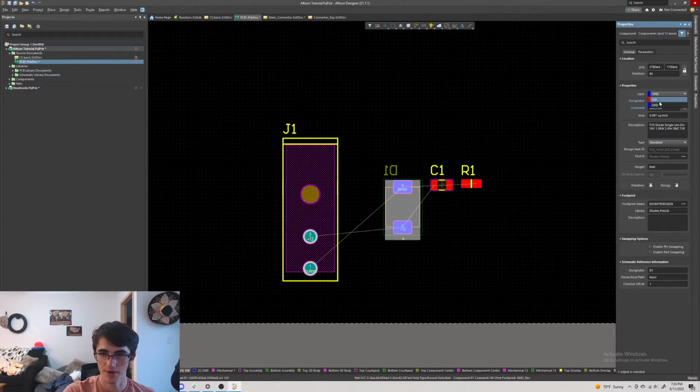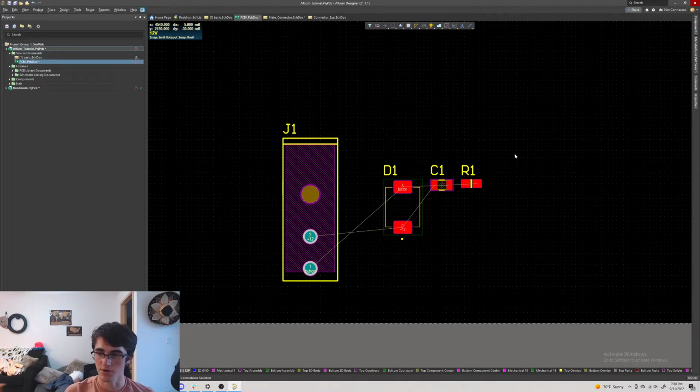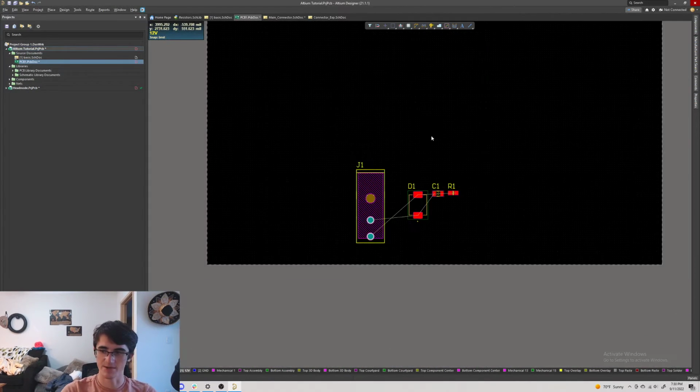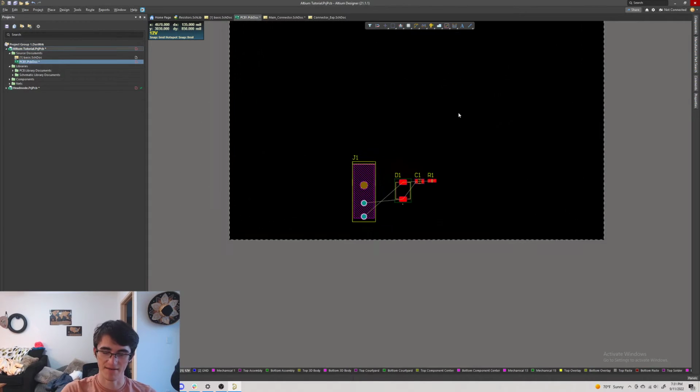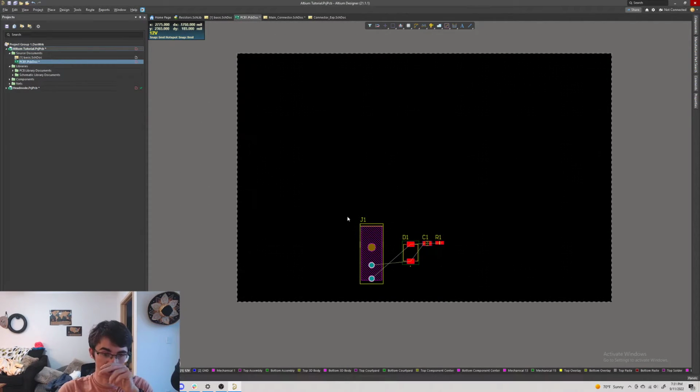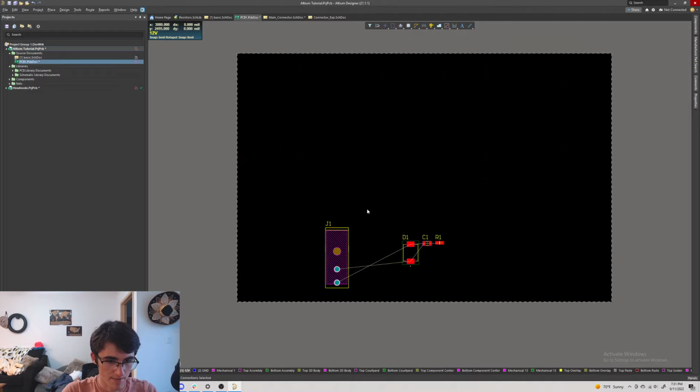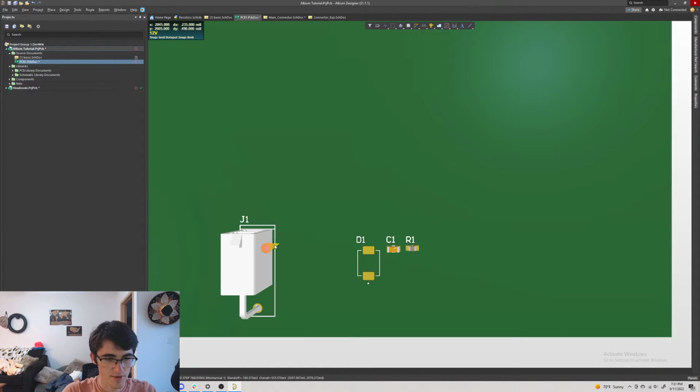Generally, if you can, you want to put all your parts on the top layer just so you don't have to have anything on the underside. It's just a risk of shorting with something, coming in contact with it. But if you need a little extra room on your board and you don't want to make it larger for size constraints, it's a really good option, especially for experimental parts or something where you might not have it on after testing.